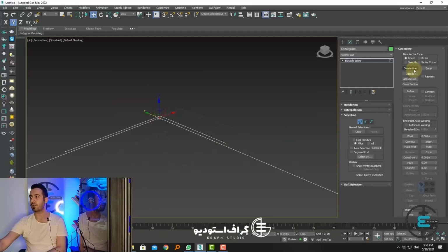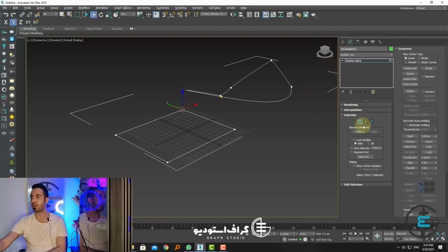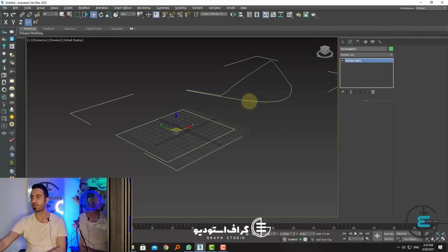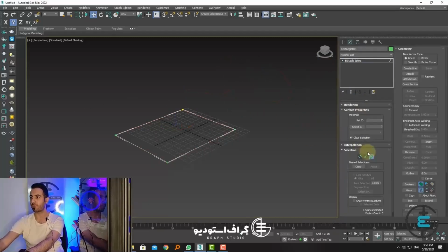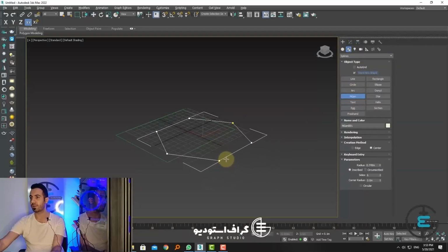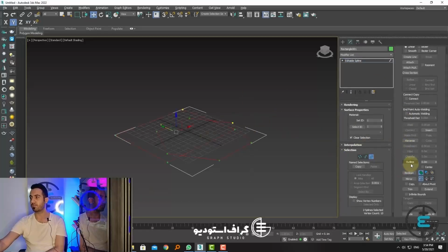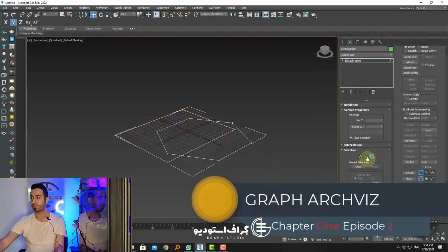For example, I select these and perform the trim operation on them. I close it. Again, draw one shape, convert to Editable Spline. Well, active vertex, you know Create Line, the same line drawing with attach, and attach is what you know. Attach Multi, we also said attach all, meaning if you have 10 splines here, you no longer need to click one by one, you press Attach Multi and select them from the list here. We just want to introduce these to you.